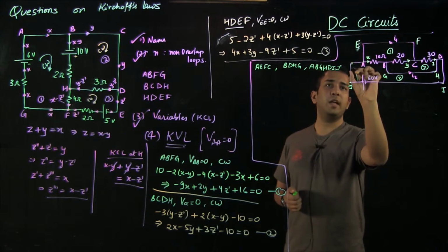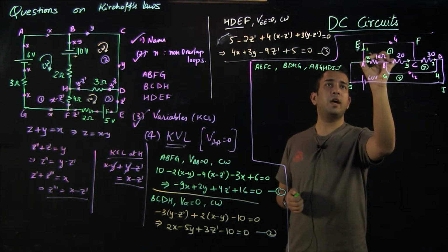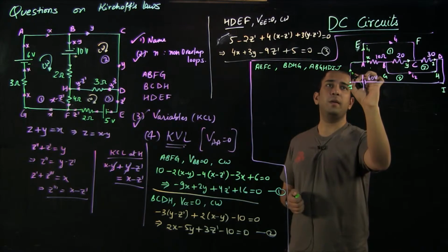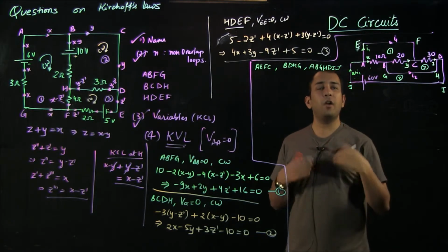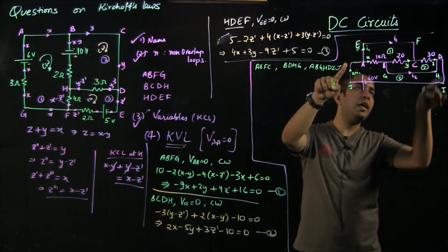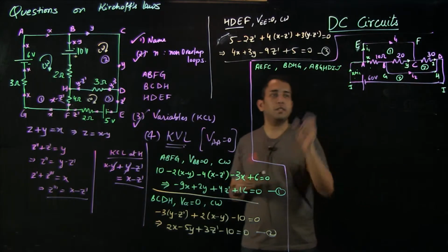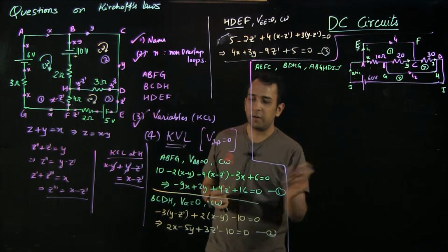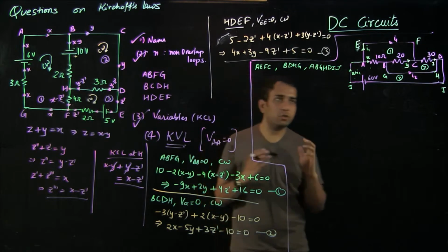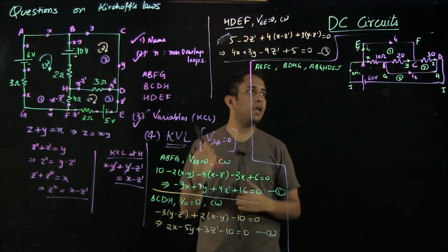The current incoming at junction A can be found because we know that the current in this branch is I1. So in this portion the current will be X plus I1, but it will not be required because in the branch A, J, I, D we do not have any resistor, so we will not be introducing this current variable, because there is no voltage drop or voltage gain associated with a resistor.